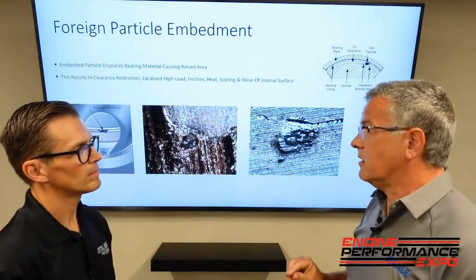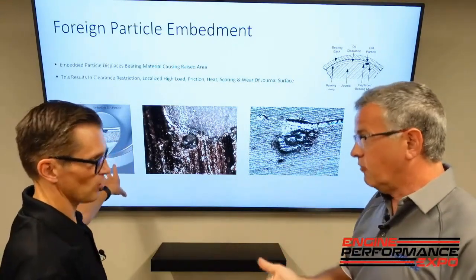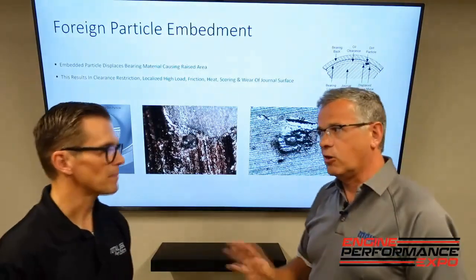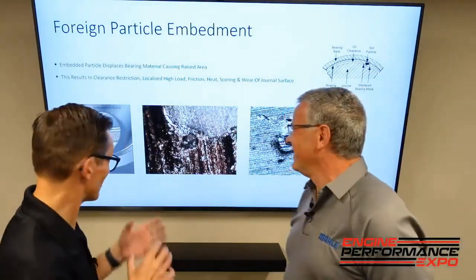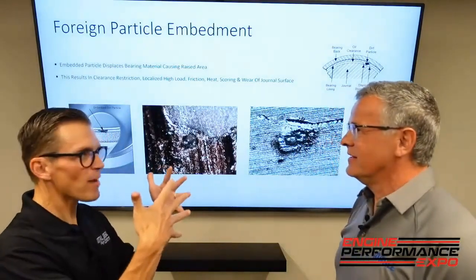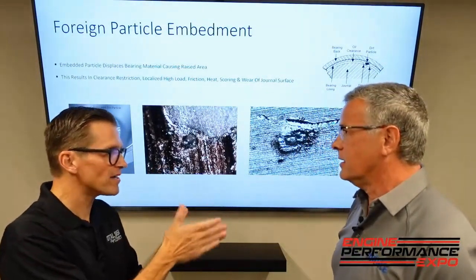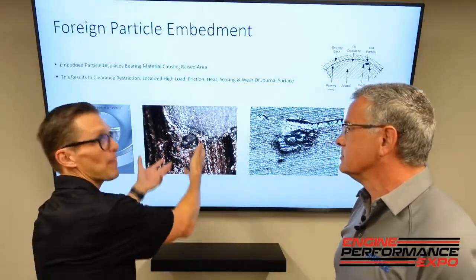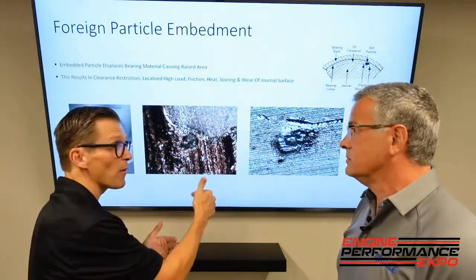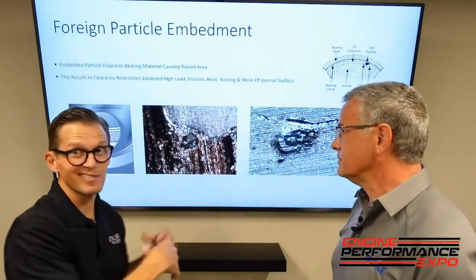And when that gets in there, you're disrupting the oil flow. Right, exactly. It's all about the oil. I love these conversations because it is the oil and the bearings, they work together. That hydrodynamic oil wedge, anything that disturbs it is like a boulder that creates a rapid. So it's not smoothly flowing anymore. We've got turbulence, and that's not good.